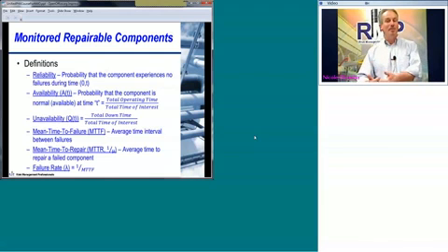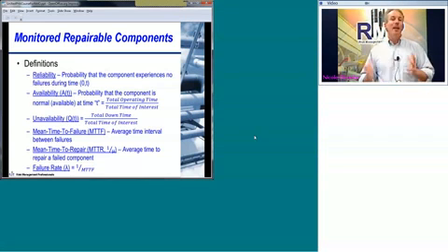The safeguards are typically represented in terms of an unavailability, basically the fractional time that specific safeguard is unavailable. Because the numbers are low, it simplifies the statistics and allows you to do the calculations a lot easier. And that's the value that you're typically using to correlate to your risk ranking matrix.